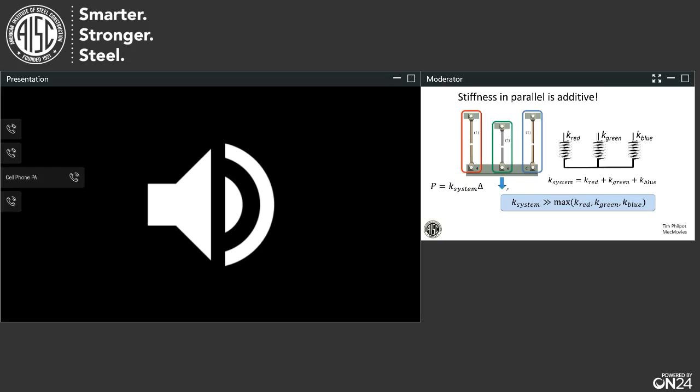And then if the engineer is aware and purposely designing the connection as semi-rigid, maybe the engineer or an alternative company is designing the connection to be partially restrained, then I am going to absolutely make sure I include the stiffness of that partially restrained connection in my computer model. I may include it and find out it has no effect, or I may conclude that it's just one connection in a building that has a lot of different alternative load paths, so it probably won't have an impact. But I definitely would pause and give it some thought. So good question, hard one.